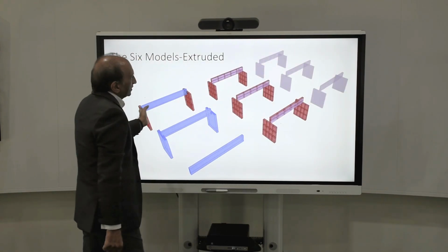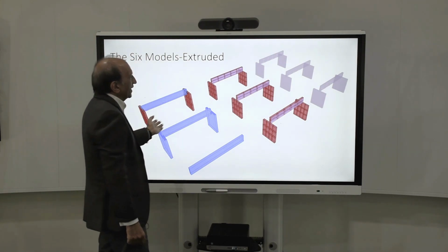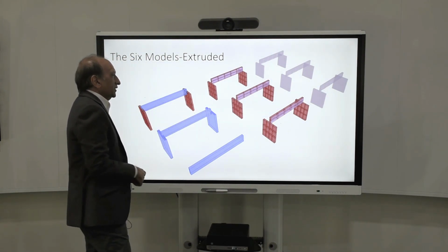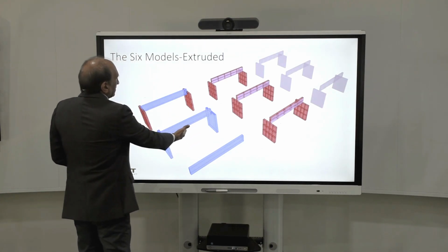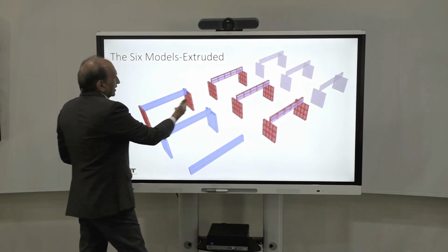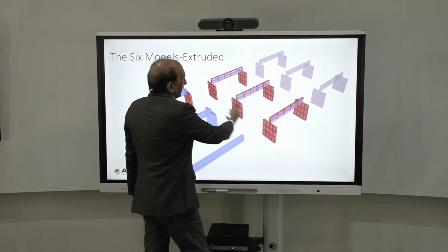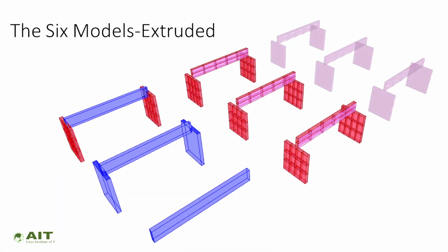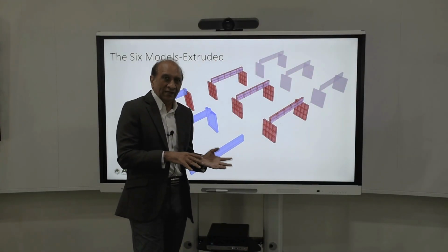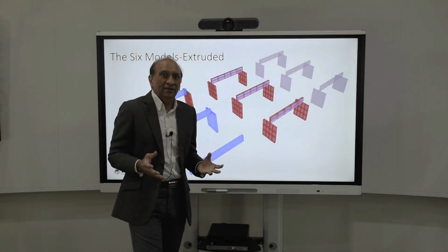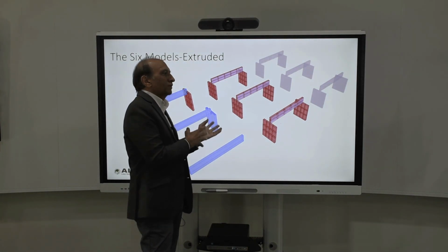So if you look at that in SAP, for example, you could make different types of models for the same thing. This is a simple beam. I represent it in an extruded form. This is a beam, center line on wall, beam on shells, and then different models of shell on shell and full solid models. You can create them in SAP if you like. For this simple structure, we can have several options, each with some disadvantages, and they can all handle some loading and cannot handle some loading. So none of the models is actually really solving the problem that we started with.